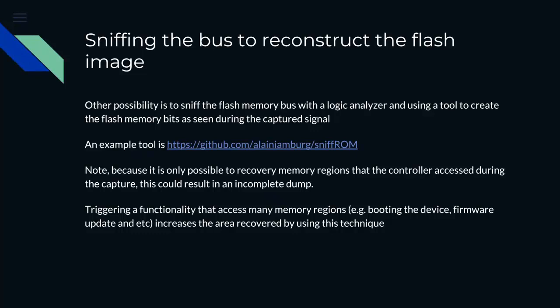That is a problem though, because you cannot be sure that the microcontroller running as it is would access all the memory, so you basically want to capture on your sniffing the commands of that part. Some ways to cover most of the memory are to try rebooting the device or performing a firmware update. That increases the area that you are going to be able to recover.